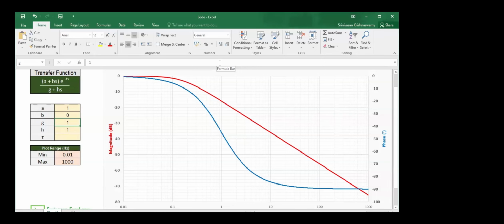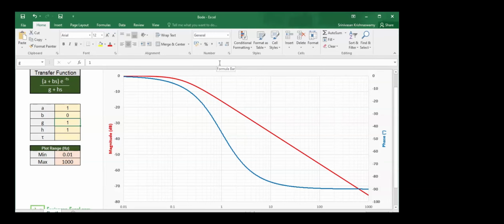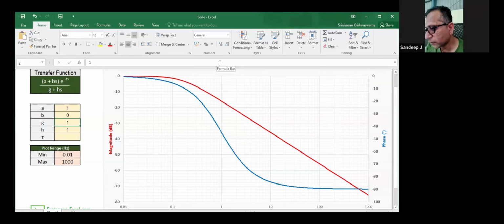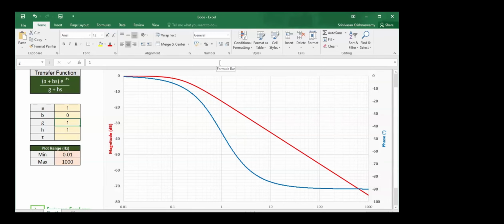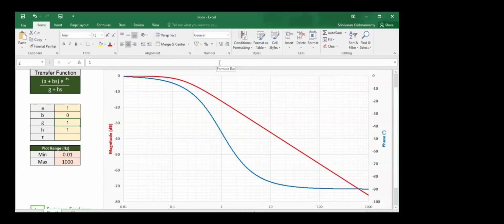Can I say feedback is something unfortunate? Yeah, it's unfortunate in the audio world that feedback is perceived that way. There is a term called TIM, transient intermodulation distortion, proposed by Dr. Otala. When you have heavy dependency on feedback, there is a time difference between the correction applied and the actual event. Exactly. During that period, it causes intermodulation distortion. So excessive feedback will not sound right.